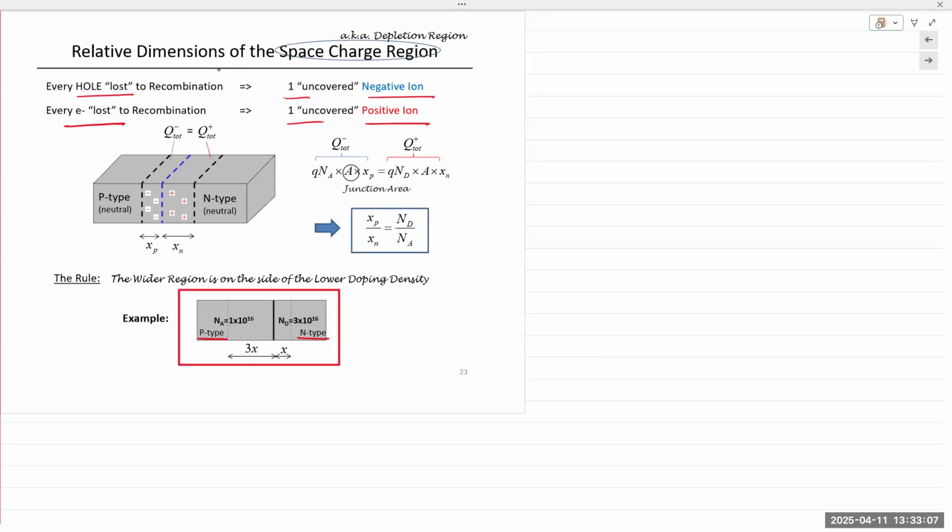of the junction. The junction is right here in the center. That's the junction. X is the distance as measured from the middle of that junction. The junction point is 0. Xn and Xp are how far into the material the diffusion occurs, the space charge region. So if N has a higher concentration, then Xn will be lower than Xp.